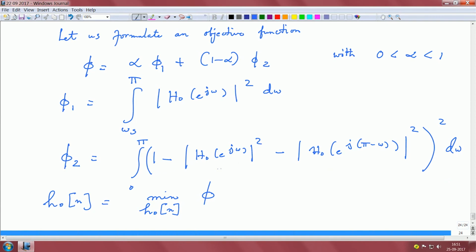So this is like your error, error square is what you set up here and I want to minimize this error square. Okay. So, these are some objective functions, and one such function is this. So this gives you a gamut of choosing your alpha just from the tail, that is from the stop band to pi, versus looking at the entire band from 0 to pi,